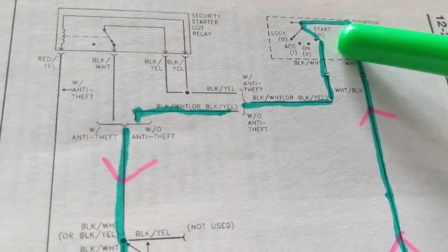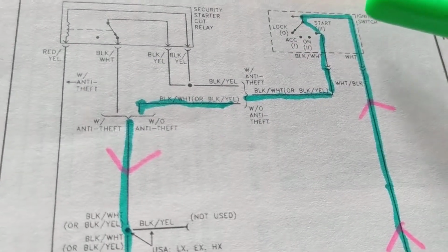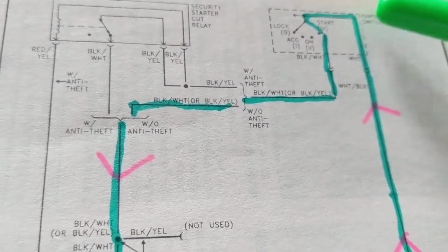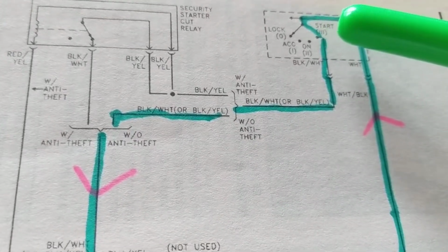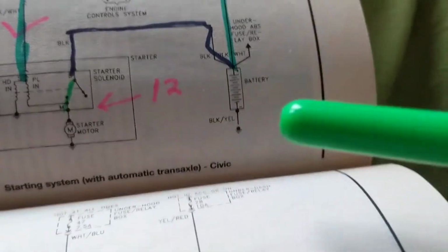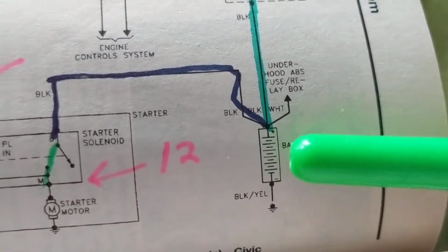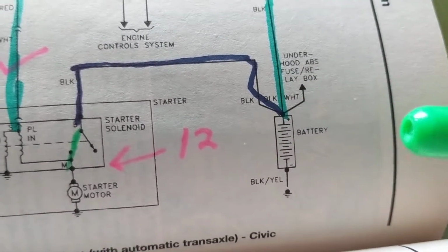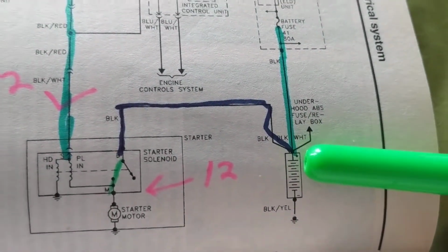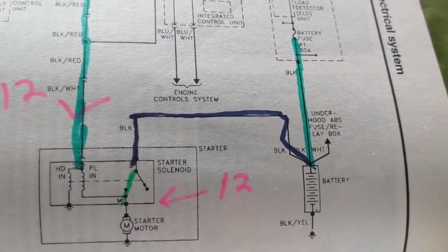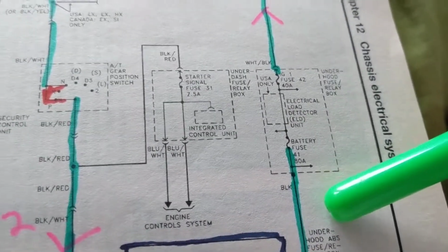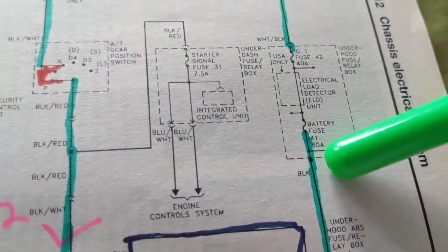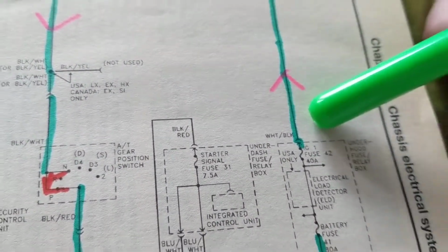So, is it different from the other ones? No, same concept. You still need an ignition switch like Chevys, like BMW. You still need it in every car, right? Same concept so far. So, we started from the battery, right? Remember, you call it 6 cells. Same thing as other makes and models. Also 6 cells. Why? Because each cell is 2.1 volts. 2.1 times 6 gives you 12.6, which is the voltage of a good charged battery, depending, of course, on the heat and the temperature.